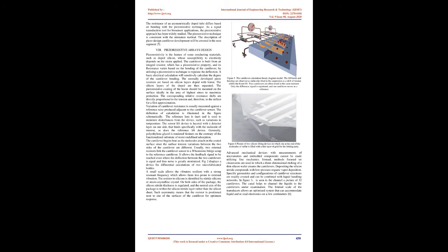The benefits and drawbacks of all the different signal transduction approaches depend on the procedure. In optical beam deflection, a beam of light from the laser to the tip of the cantilever is reflected to a responsive position detector, and the shift is observed. Although the optical beam deflection process is commonly used in sensor processing, the sensors are not lightweight. In the piezoresistive technique, the resistance of an asymmetrically doped tube differs based on bending. As a signal transduction tool for biosensor applications, the piezoresistive approach has been widely studied. The piezoresistive technique is consistent with the miniature method. The description of piezoresistive cantilever development will be covered in the next section.